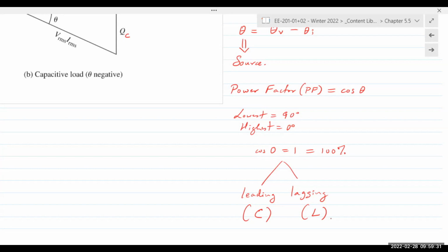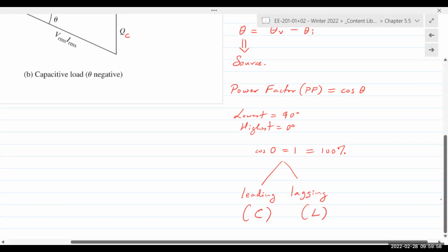And the reason is, when you first flip the switch on, what is going to happen? The utility company sends all of that power to the initial customer, right? The customer receives that inductive power, and it wants to bring that power factor up or the angle down. You want to bring that power factor up. You want to reduce this angle. So the way to reduce the angle